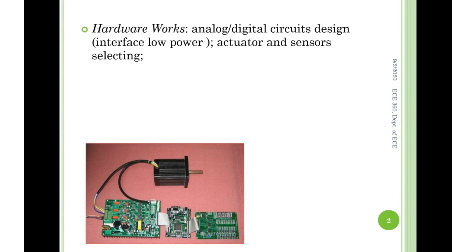Very, very low power. Generally speaking, what is the current rating? The current is absolutely much lower than 1 ampere, not even 100 milliamperes. Generally speaking, tens of milliamperes. Very low current, very low power. That makes perfect sense that we are not even using a heatsink or any fans to help air circulation. We don't need extra equipment for heat dissipation.